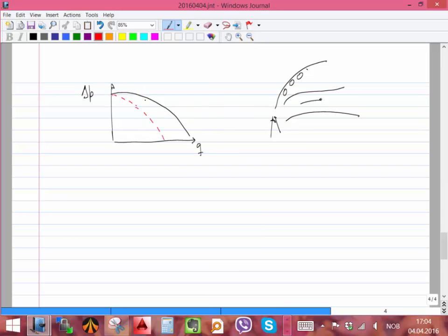The thing is that with viscosity, if it's a single phase, we're able to predict exactly how it will look. When we have multi-phase flow, no question. Could it be like that? Could it be like this? Could it be like that? Nobody knows for sure. The only way is to measure it, to actually put those properties, that viscosity, that density, and measure what it's going to do with the machine.